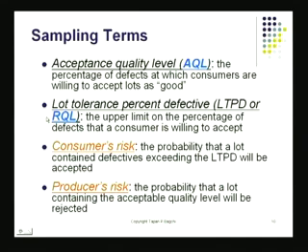Now, the distinction between the two, AQL and RQL, is the following. A lot quality which is at AQL level is good enough for me to carry on with my routine production. Yes, there will be a few defectives there, but I'm willing to live with that because I'm not doing 100% inspection and I'm really banking everything on the acceptance sampling plan that I put in place. Yes, I do end up with a few defective parts in my production, but I remove them or I do some rectification and so on, and I live with them.